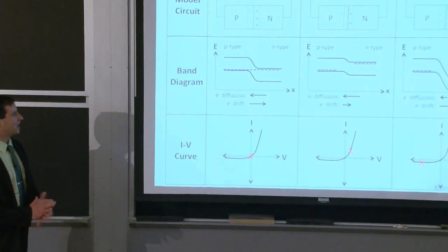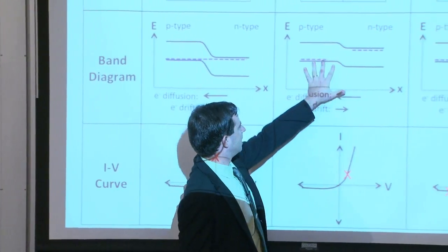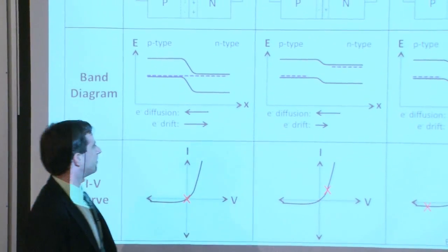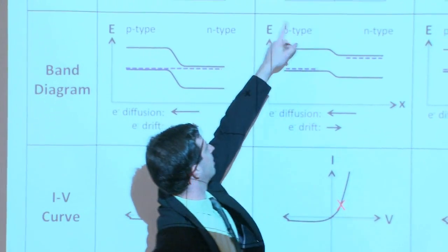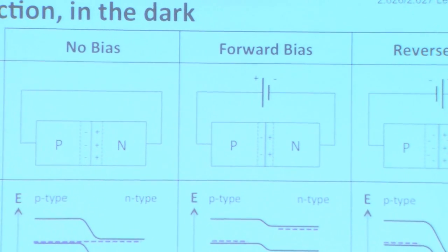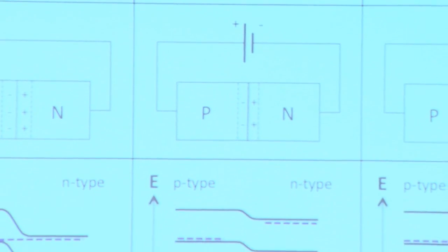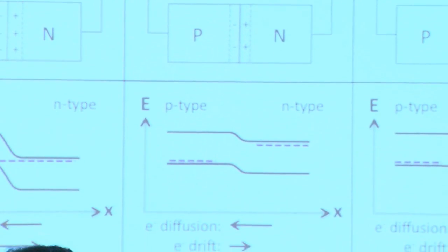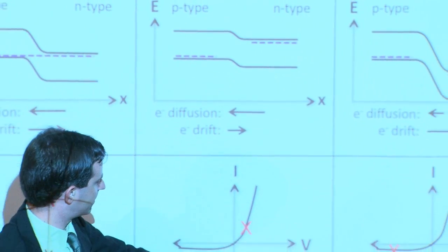Great. Okay, now what happens if we forward bias our device? Either because we're adding a resistor in series to our solar cell, so instead of a battery there, you would replace that with a resistor, or if we're applying a bias voltage as well, we could also do that under illumination. So we'd still have the illumination current, right? And we'd, through superposition, shift this entire curve down.